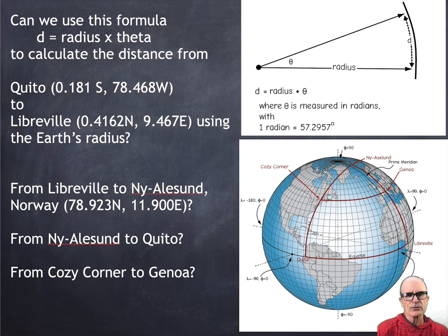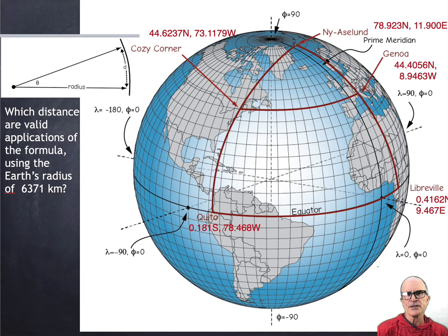The latitudes don't. So I have to be careful in using this formula that I apply it correctly. Like, this is not valid because it's a small circle. It subtends this line. It's great for an approximation. In the book, and later on, we talk about closed form, more accurate solutions for any coordinate pair that we have. But this is good for just rough estimates along great circles or for small distances.